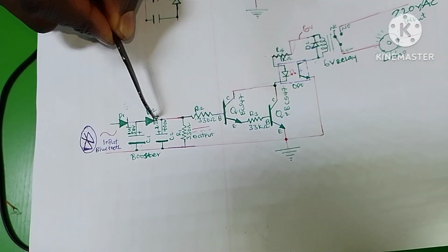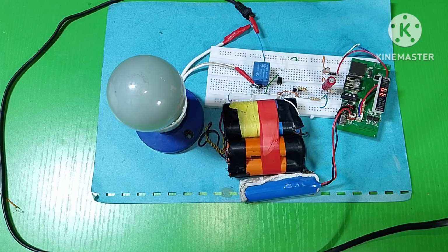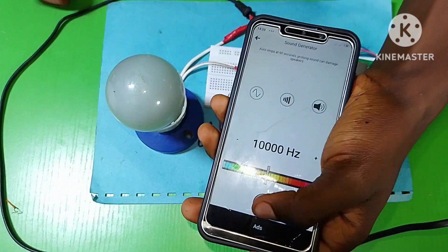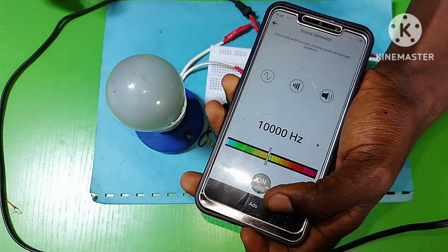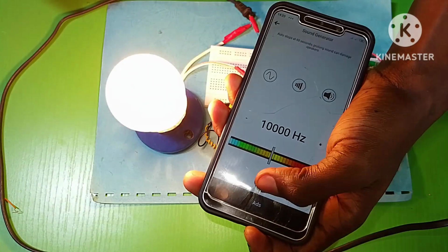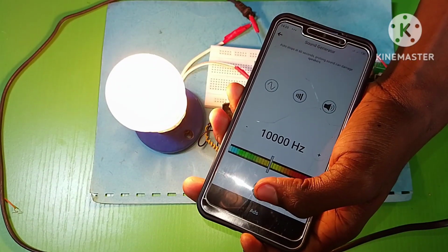So here is the resistor we needed to add across the capacitor so that it could discharge immediately. So now it works better. You can add a higher value than mine so that yours can work even better than mine.